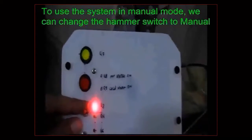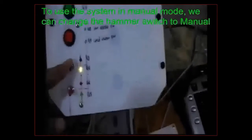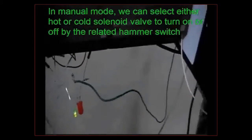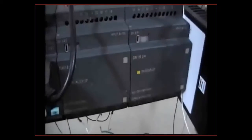And as I said before, by putting the hammer switch down, we can go to manual mode, and in this case, right now, the cold water valve is turned on. Because this is a relay module, you hear the noise coming from the on and off of the relay. And when I put the hammer switch up, the hot water valve is turned on.